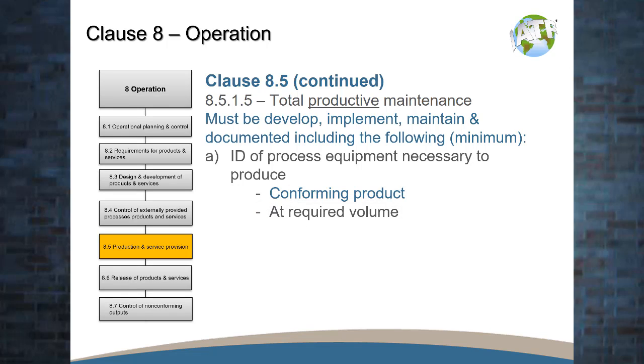What is the takt time? What is the material flow as it is being pulled by the customer, and can your equipment handle that volume or that count? B, availability of replacement parts. So you should have key replacement part inventory that's adequate to ensure that your equipment is not only suitable but available as needed should a part of that equipment need to be replaced.